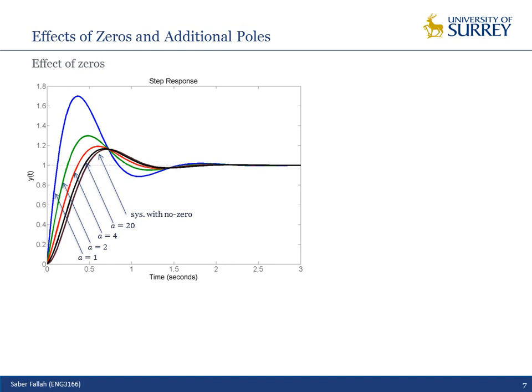But isn't it when you underdamp something, you increase the rate of response? Yeah, if you have the underdamped system, you have some oscillation, but faster oscillation. You know what I'm talking about? I will show you some examples. So you are saying this becomes very large, which means this becomes very small. So then you have a 1. This is gain of 1, that's standard, because this again is 1. Yeah, exactly. Good.